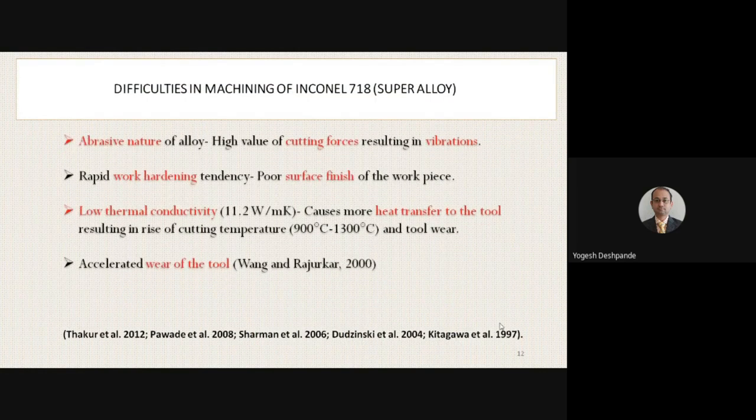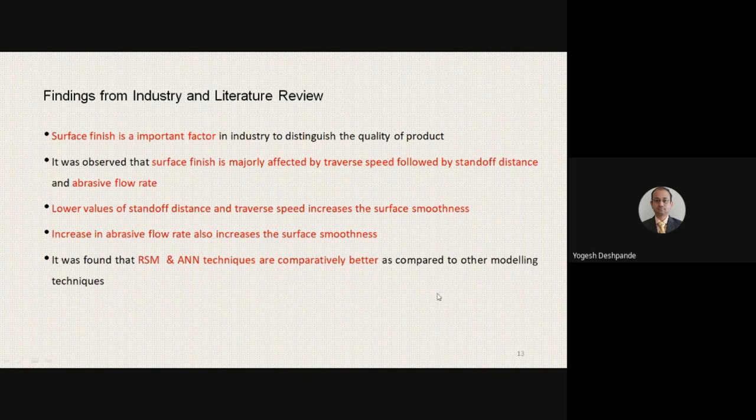Here are various advantages of Inconel 718, because of its abrasive nature and low thermal conductivity, but at the same time it poses difficulties in machining, which result in low tool life and poor surface finish. That's why machining of such aircraft material is a challenging job for shop floor industries. These are some key points recorded after literature review and industrial survey.